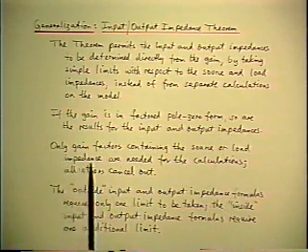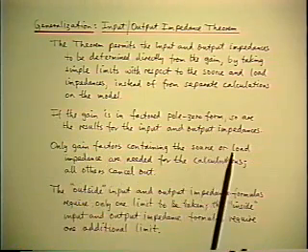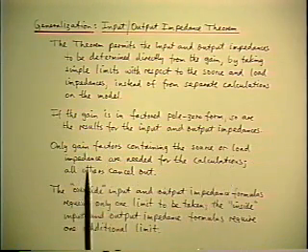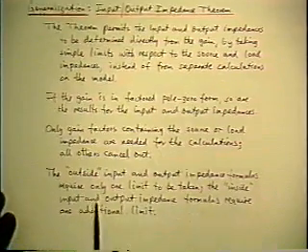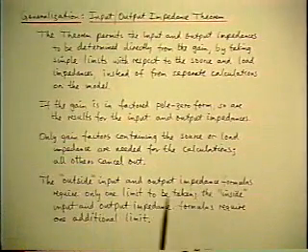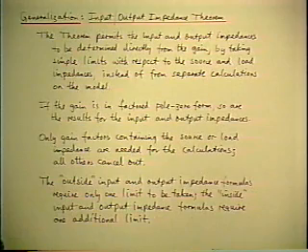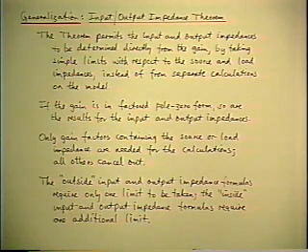You always get huge simplifications because only gain factors containing source or load impedance are needed for the result. All the others cancel out. Finally, the outside impedance formulas are simpler because only one limit needs to be taken. If you want the inside impedances, you can just take the other limit and the answer you got already.